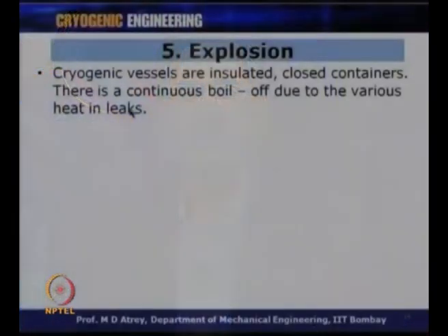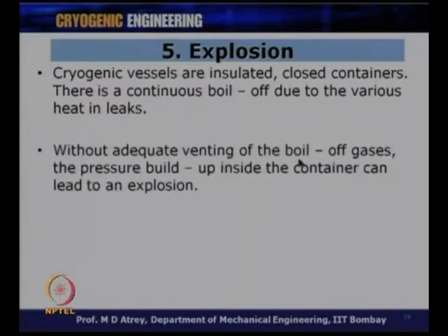The fifth one is an explosion. So, the fifth hazard after fire we talked about is explosion. Cryogenic vessels are insulated closed containers. There is a continuous boil off due to various heat inleaks. This is a well known fact. Without adequate venting of the boil off gases, the pressure build up inside the container can lead to an explosion.